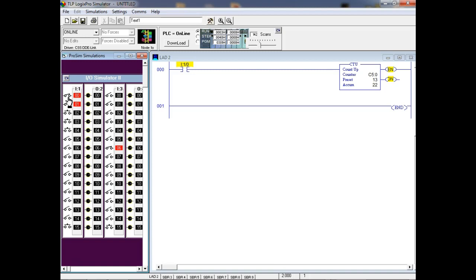So if you ever look at a digital symbol, you see that little guy right there. Now that means it's what? Edge trigger. If it comes straight in, it means the guy's looking for this. If you put a little bubble right there, what is that? Yeah, it's looking for that guy right there. And I've seen in Siemens, you have the ability to set these things up to look for the positive edge or the negative edge. We don't have the ability to do that right here.